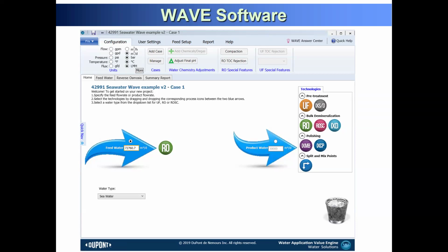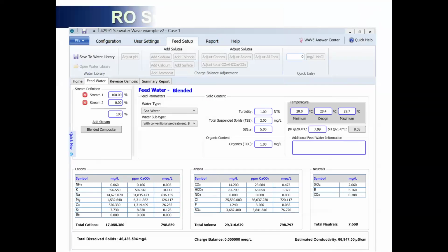The permeate final product is our target, which means you need to produce product water of 250 million liters per day rather than feed water. So at 50% recovery, how much feed water do you need to calculate? You can think about what's the best way to utilize the feed water.